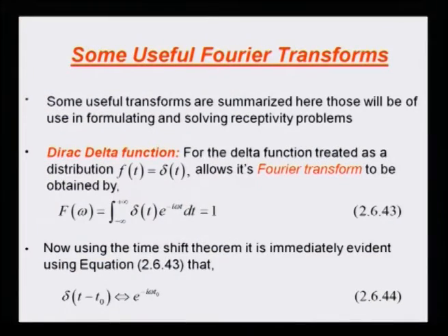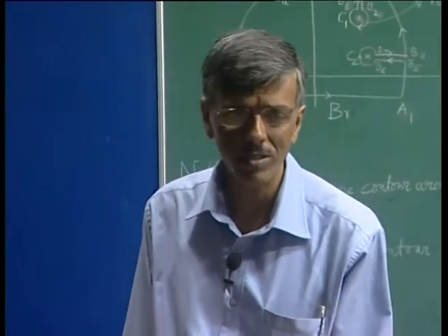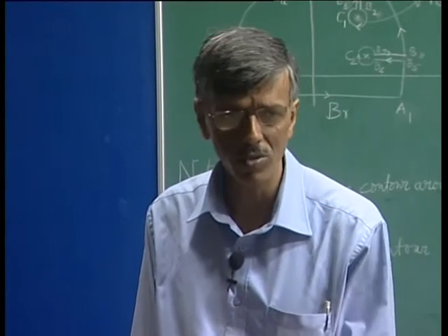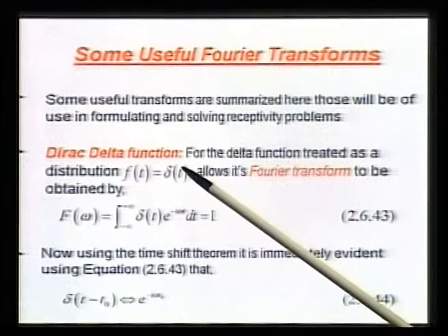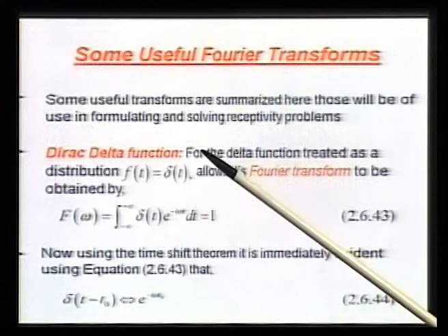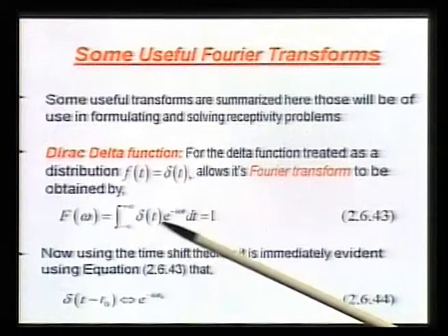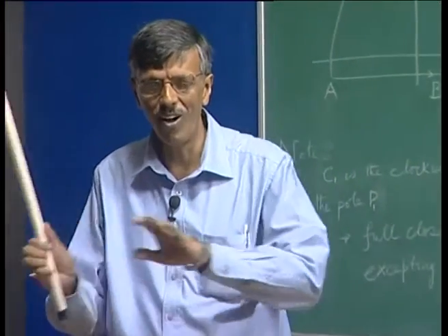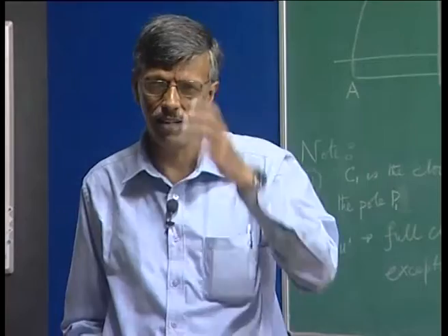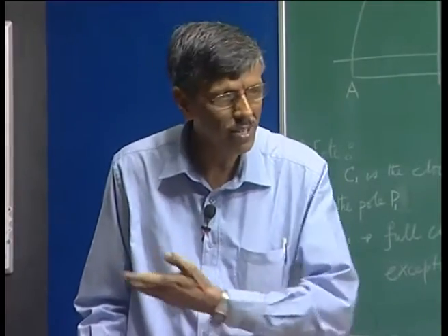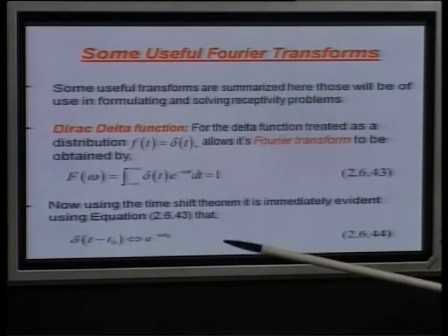Okay. So, this is what we have talked about in the past when we were discussing frequency response versus impulse response. This property, as you can see, is that if I create a delta function in the physical plane, so I am just giving an excitation at t equal to 0, that fills up my frequency plane completely, and they are all weighted equally, there is no bias. So, if you are trying to look at, let us say, the natural frequency of the thing, you excite the whole system with all the frequencies and the system will pick up its natural frequency.